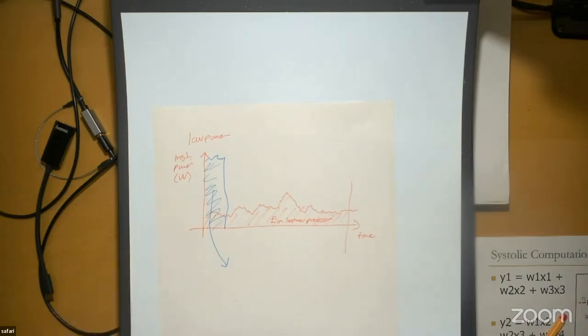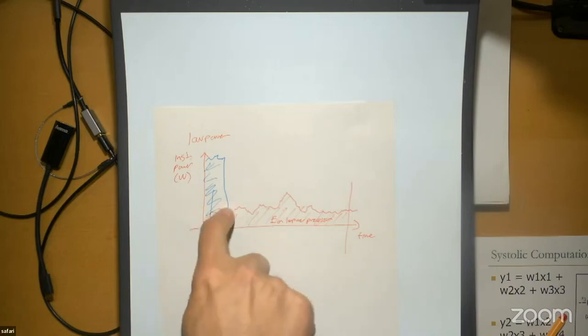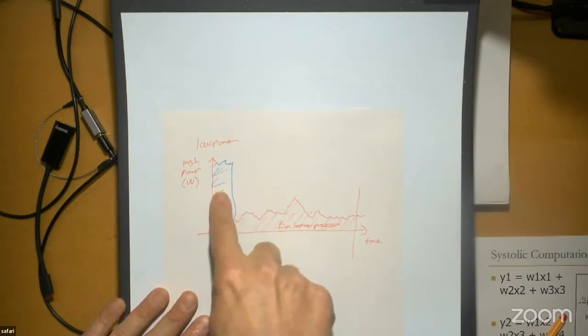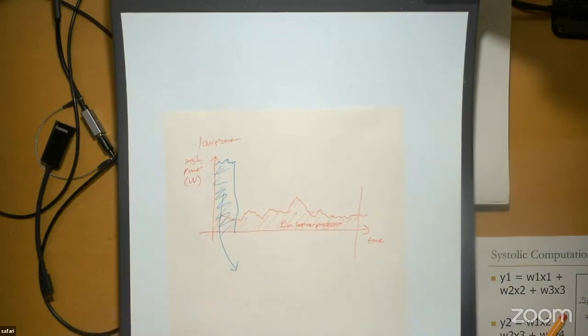So what is the implication of this? Energy is actually what determines your battery life in the end. That determines the draw, because your battery has limited energy capacity. And in the end, this high power processor that finishes your program much faster can draw some energy and then go to sleep, right? And then it doesn't consume any energy, whereas this processor consumes a lot more energy.